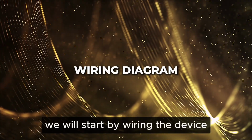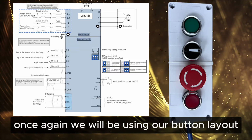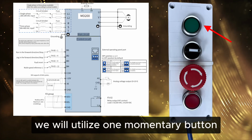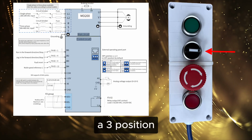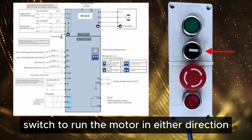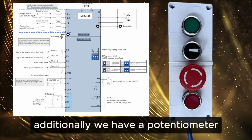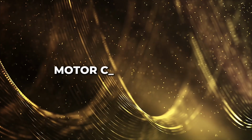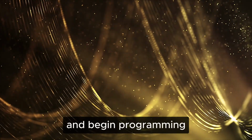We will start by wiring the device. Once again, we will be using our button layout, of which we can only use 4 out of the 5 inputs. We will utilize one momentary button for the purpose of jogging, a 3-position switch to run the motor in either direction, and an emergency stop button. Additionally, we have a potentiometer plugged into the analog input slot. Once finished, we can now power up the drive and begin programming.